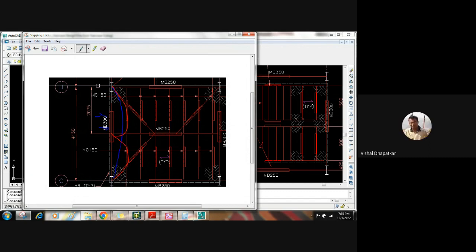Because this bracing will provide a restraint, right? When it tries to buckle or bend, what happens? There will be an axial force getting generated. This axial force will be passing through this member, but at the same time that force is getting transferred back to the column, right? That's why it bends or it deflects like this, right? If there is no bracing, then it will buckle like this, for a complete length, not for the half length. So whenever we have a bracing, then Ly gets half or according to the length of the bracing.